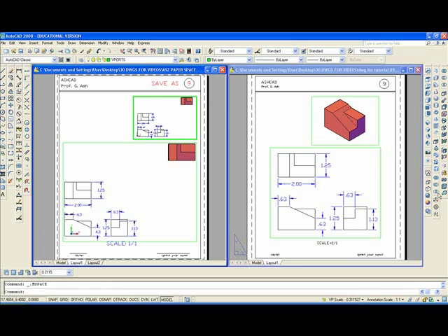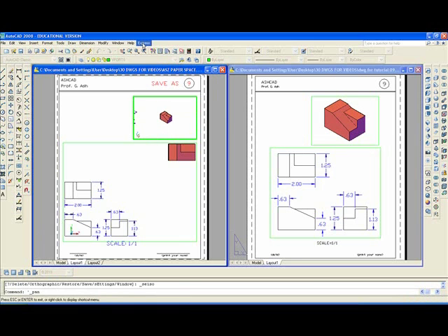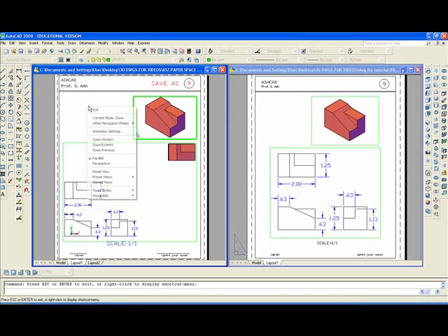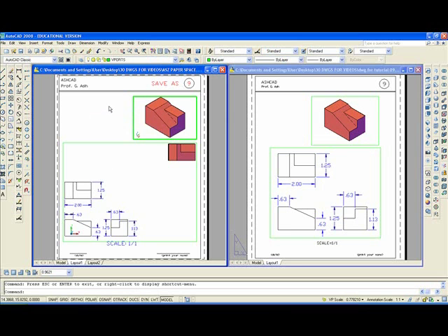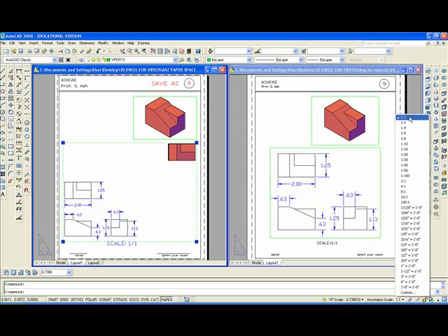Double click inside, then go to Southeast Isometric, pan, and zoom. Zoom real time to make it even bigger. Double click outside to get back into paper space. Click on the large viewport and go down to annotation scale and select 1:1.